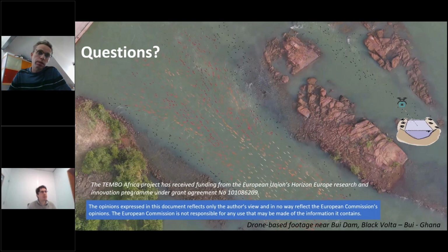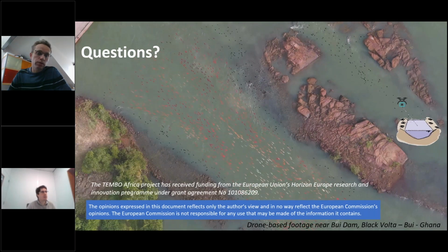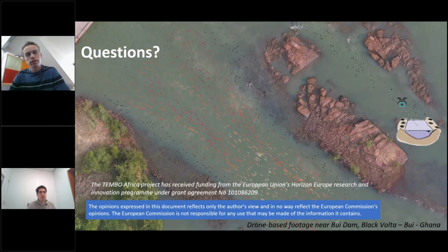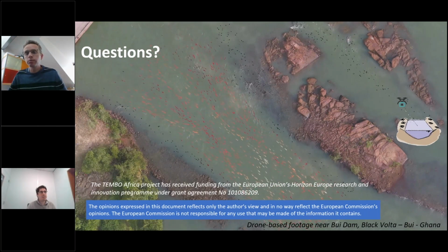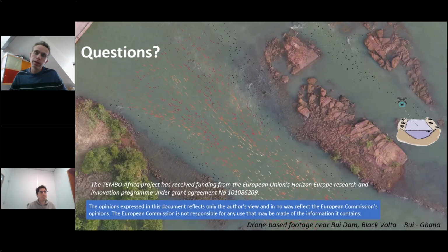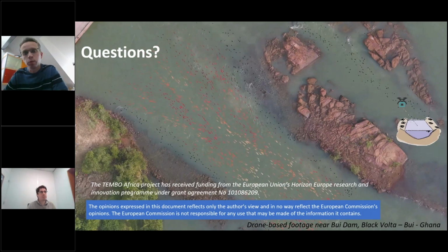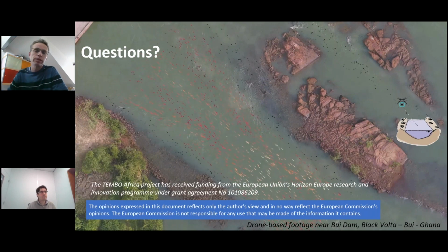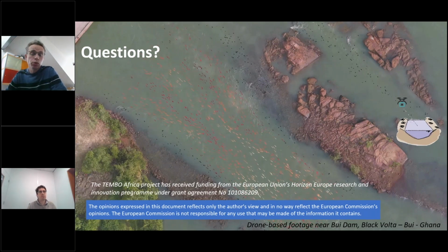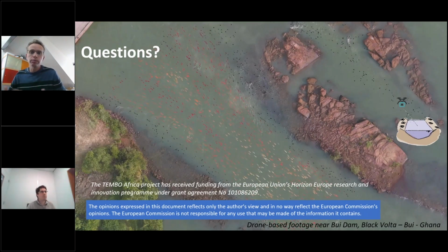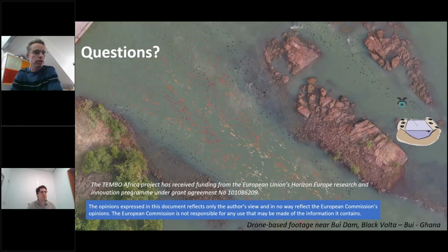But I also think that in those cases you could try to do it in a different way. You could say, okay, let's do a temporary setup with the camera to get a rating curve, and then we have a lighter and less conspicuous setup with water levels only, and we update that rating curve from time to time with a shorter survey period with the camera, where we have a little bit more control over the site and we guard it, for instance, for a while.